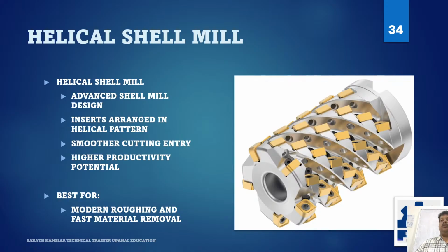These cutters are often seen in modern production machining where faster stock removal is desired. They also look impressive, and for good reason, a lot of engineering goes into the cutter geometry. This tool shows that cutter design is not only about sharp edges, it's also about how forces enter the material. So the best benefit of the helical is that it can take out flat surfaces and it can do side milling also.